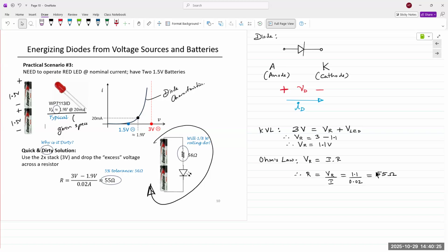Okay, so anyone have a coin battery at home? A coin cell or a button cell, you know what I'm talking about, right? The smaller button cells are about 1.5 volts, I believe, and the coin cells are 3 volts. You have LEDs in your lab kit. You want to do a small experiment at home, you take one of these LEDs and take the positive, anode, and just slide the coin cell between the two terminals and press down on them so that they are making contact, and the LED should turn on.